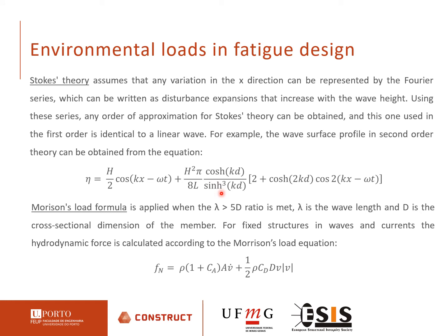Selecting the wave theory applicable to an offshore structure model is an essential step in a hydrodynamic analysis. In cases where the wave amplitude is not small or for high values of wave inclination where linear theories do not reach an adequate degree of precision, nonlinear theories are adopted as, for example, the Stokes wave theory.